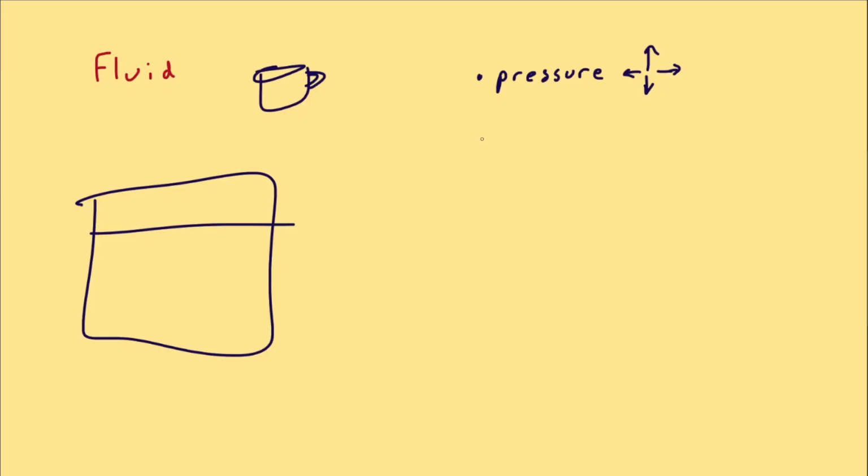The second thing special about fluids at rest is that imagine a tiny cube, a super tiny cube of this fluid. All the pressures on all sides of this fluid must be equal. They must all balance out. Why? Because if one of these pressures were bigger, then that would create a net force and your fluid would start to move, which contradicts our assumption that the fluid is at rest. So all pressures are equal.